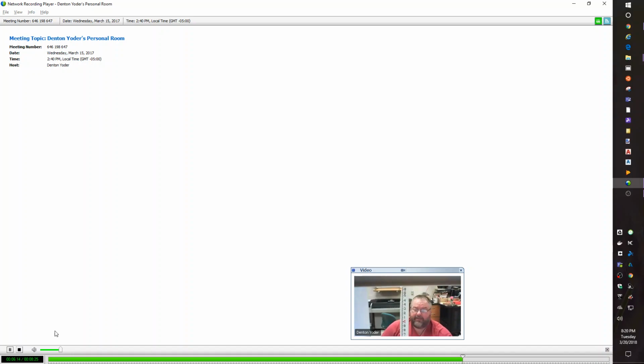If you're using the optical level and you're using the numbers, standard practice is for the person holding the rod to rock the rod forward and backward slowly, towards the instrument. The person looking through the instrument will see a sliding value based on your rocking.